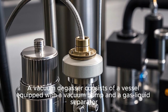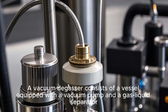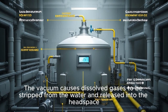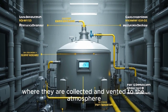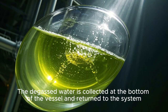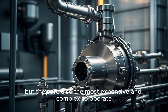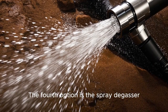A vacuum degasser consists of a vessel equipped with a vacuum pump and a gas-liquid separator. Water is pumped into the vessel, and a vacuum is created in the headspace above the water. The vacuum causes dissolved gases to be stripped from the water and released into the headspace where they are collected and vented to the atmosphere. The degassed water is collected at the bottom of the vessel and returned to the system. Vacuum degassers are the most efficient option for removing gases from water, but they are also the most expensive and complex to operate. The fourth option is the spray degasser.